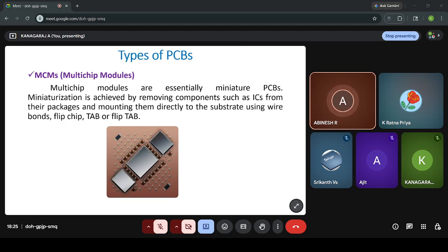Here you can see the silver-colored module, only the chip is visible on your PCB board. The entire controller is not visible, because instead of using a separate PCB and connecting them with wires, we are using a single PCB. The traces of the separate ESP32 are integrated with your design. Now you can understand.